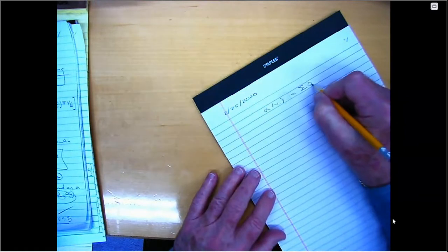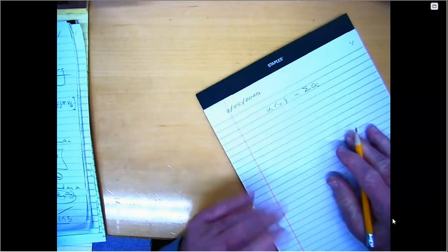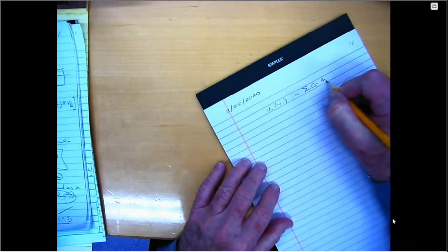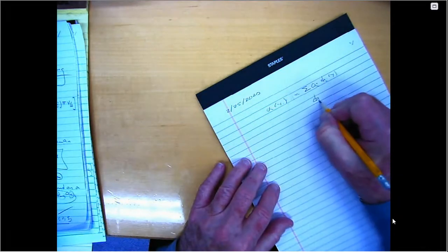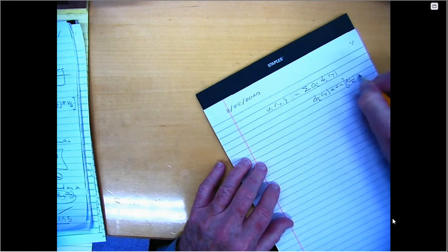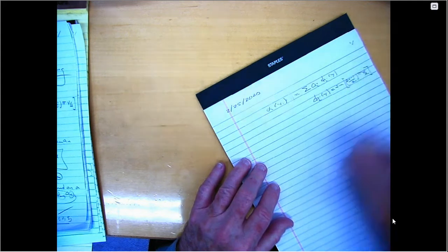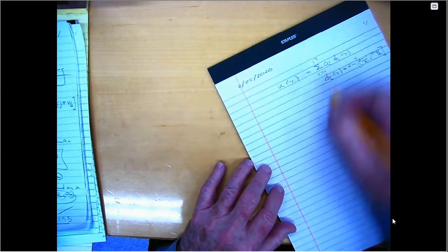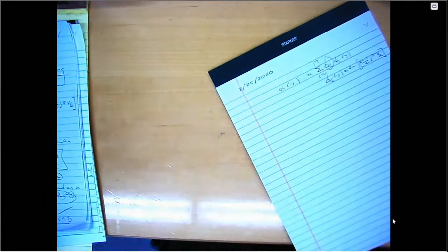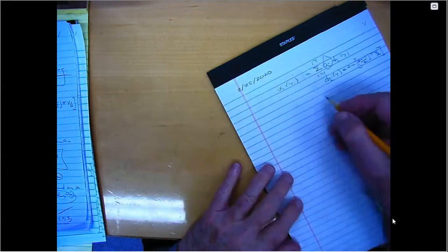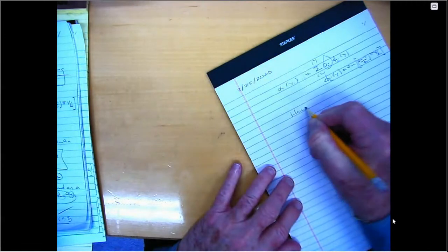And so it's going to be some coefficients a sub I, which are not functions of time, but are at the beginning unknown, times some functions of y, where we choose these functions of y as equal to sine of (2n minus 1)/2 pi y upon l, right? And what we want to do, I equals 1 up to however many terms we have, 17. We want to determine equations for those a sub I. We have several alternatives. How do we construct equations?